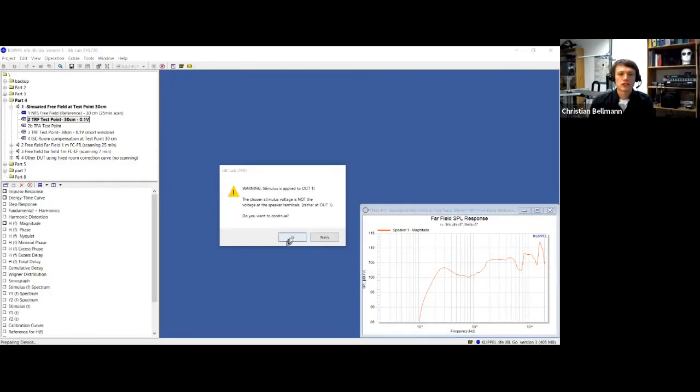Okay, what our first test is here, we are now doing a common thing. We are compensating a room correction function exactly at the point where we are measuring. So we are at 30 centimeters, and the first task is we try to get a free field response at 30 centimeters. Okay. So maybe we just try to restart. I mean, sure, it's always the thing with live measurements.